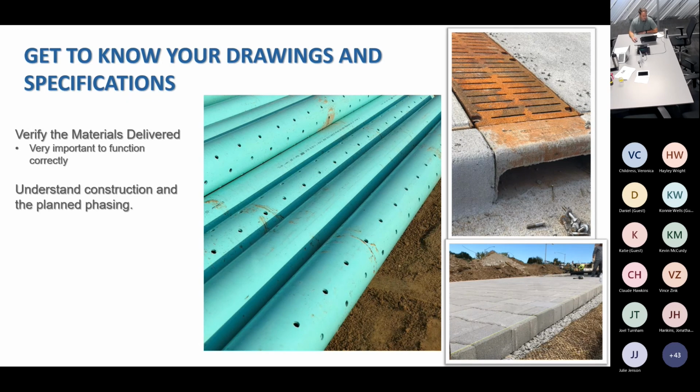Understand the construction and the plan phasing. So as these materials are brought to the site, make sure that they're stockpiled in the correct location per the site activity plan, and they're not tracking or destroying their erosion control as it's set up. And ask questions. If something doesn't look right, bring that awareness to the project manager or the contractor superintendent.